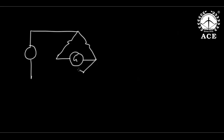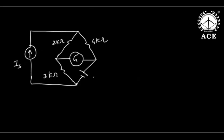See, now because of that substitution theorem, the advantage is, I will take the same network: 2 kilo ohm here, 4 kilo ohm here, 3 kilo ohm here, 6 volts, and automatically we know because the bridge is balanced, this is also 6 volts. Now I will substitute this 6 volts in terms of IR. So I will remove this and substitute in terms of IR. So now it became a resistance problem.